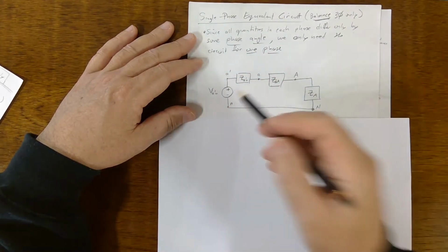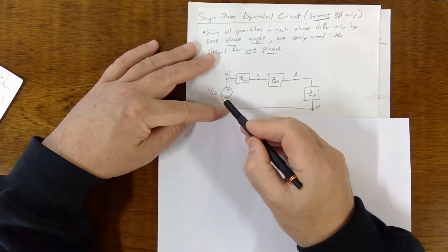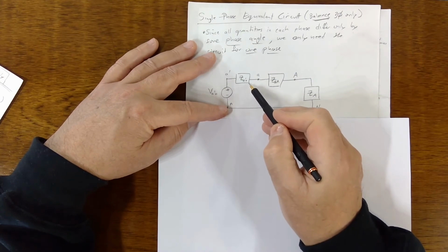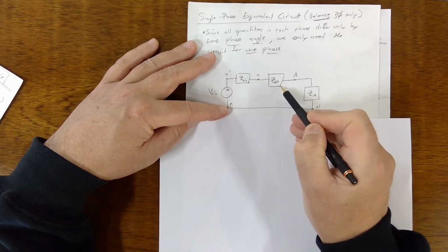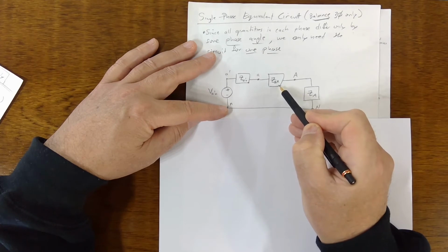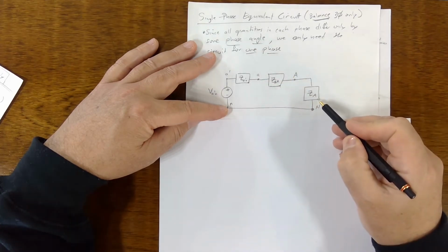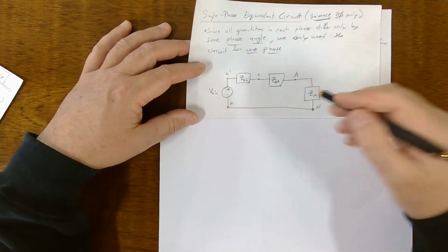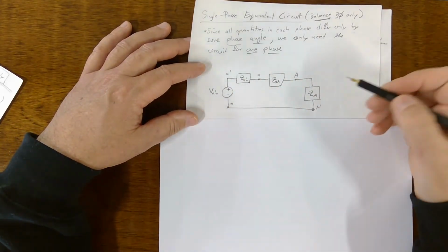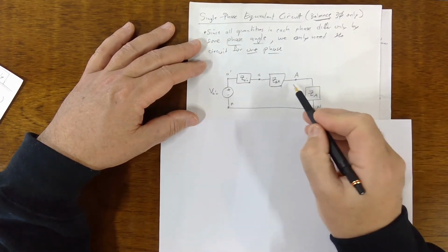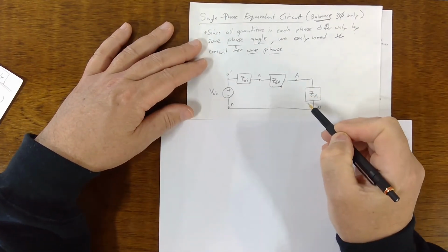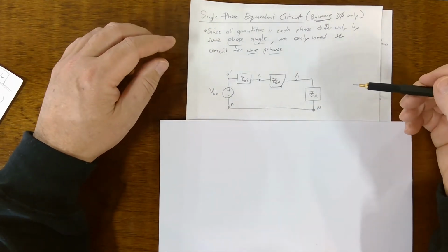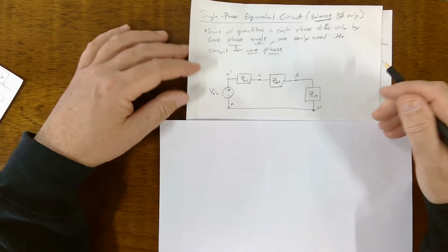So we just drew the A phase here, and here's the VA generator voltage. This is the impedance of the generator windings. This is the impedance of the distribution line, the power line, and then this is the impedance of one of the three-phase loads. Okay, so this is a simple circuit, one loop that we can analyze, and then once we have the voltages and currents in here, we know the answers to the other phases because they're off by various angles, 30 degrees, 120 degrees, all right?